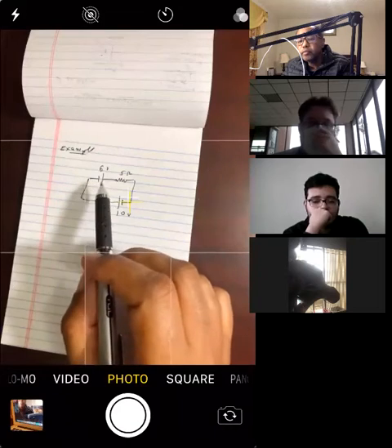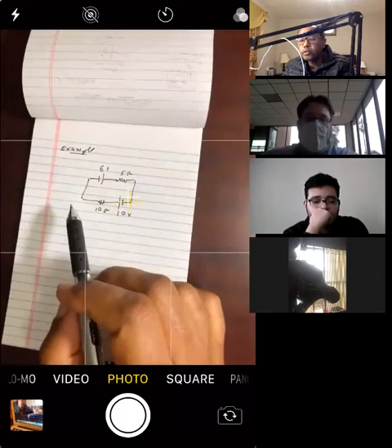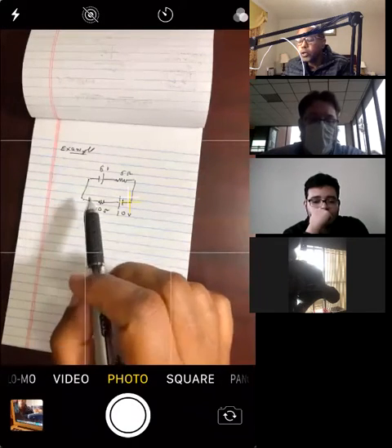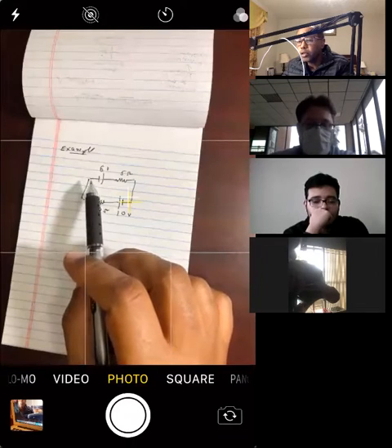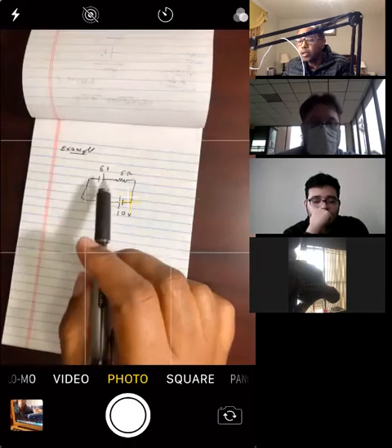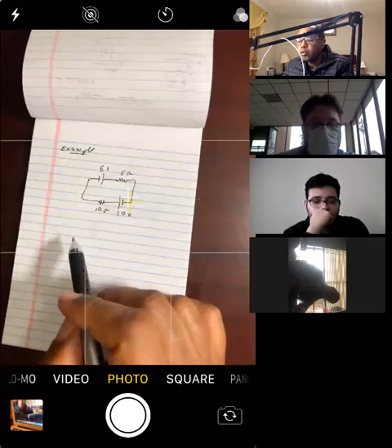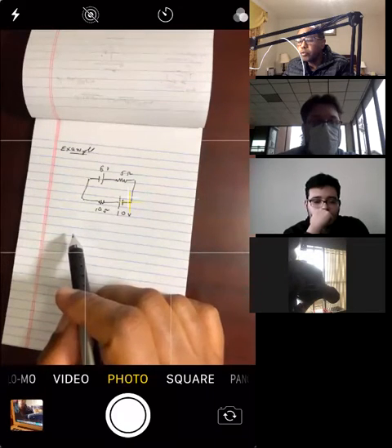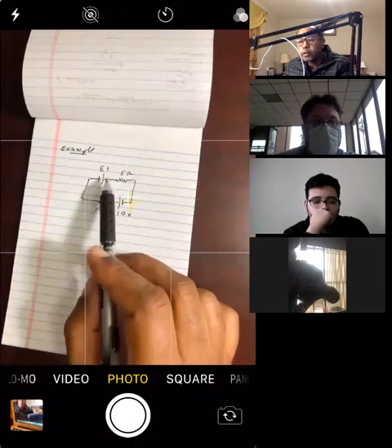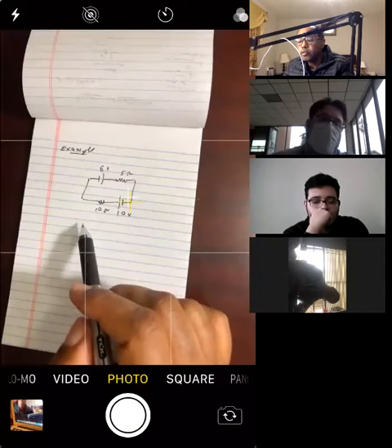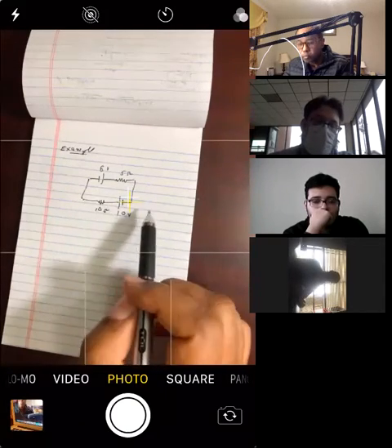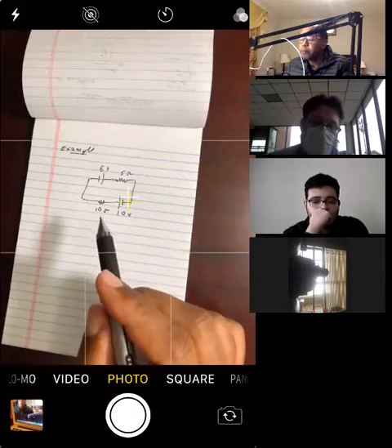If your answer is negative, the direction is opposite to the one you chose, okay? So you don't have to know the direction of the current beforehand. The answer will tell you. If your answer turns out to be negative, your assumed direction was wrong. You have to reverse it, okay?